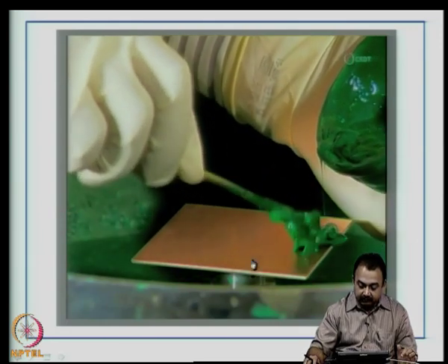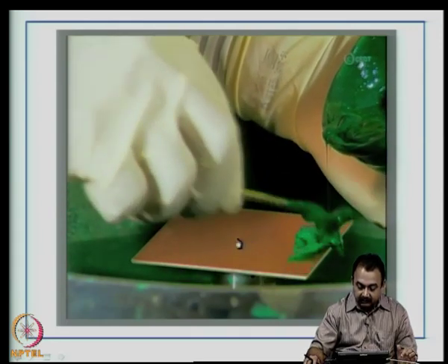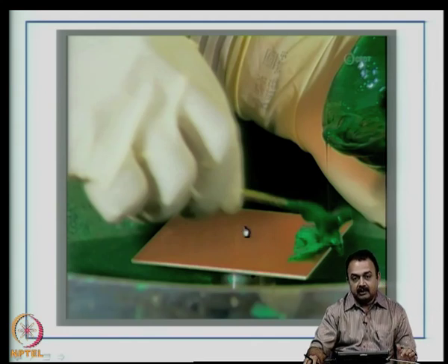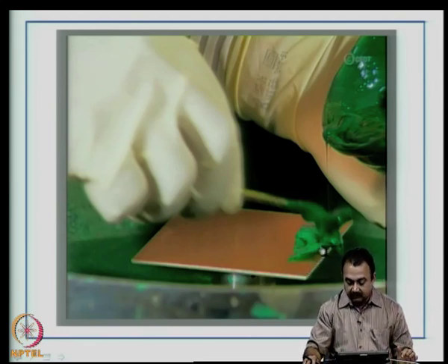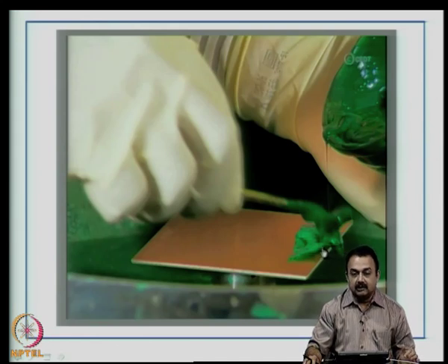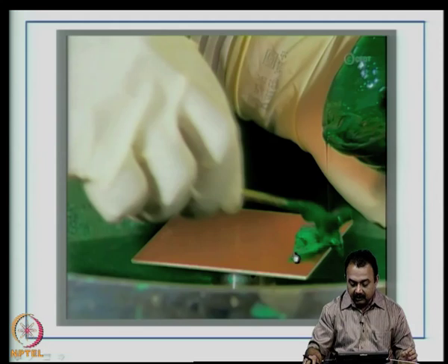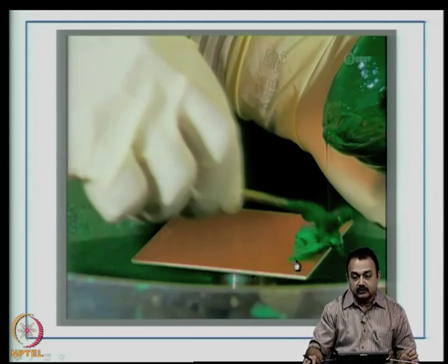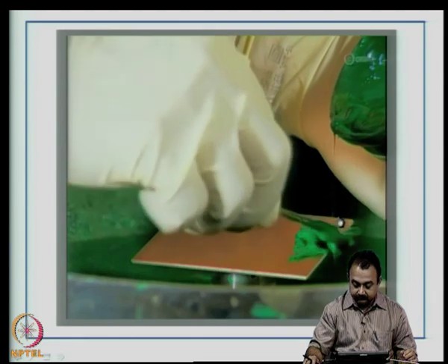Normally, you will see that the material will be poured at the center if it is a thin liquid. In this particular case of demonstration, this is a fairly thick material. This is a photoimageable solder mask. This is a dielectric material and we are showing you how you can manage to spread this even if it is thick on this area of the printed circuit board by making some adjustments.